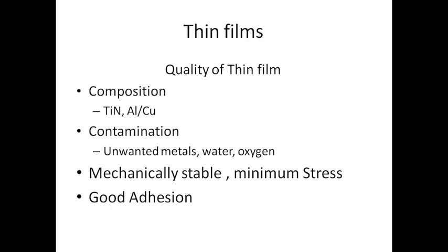And once we deposit the thin film, it should be mechanically stable, and there should not be any stress on the thin film. If there is any stress, or if it is not stable, then we cannot do further processing on the same thin film, because when we are fabricating an IC, so many layers have to be fabricated one over the other. If the bottom layer is not stable, then it becomes very difficult to have the subsequent